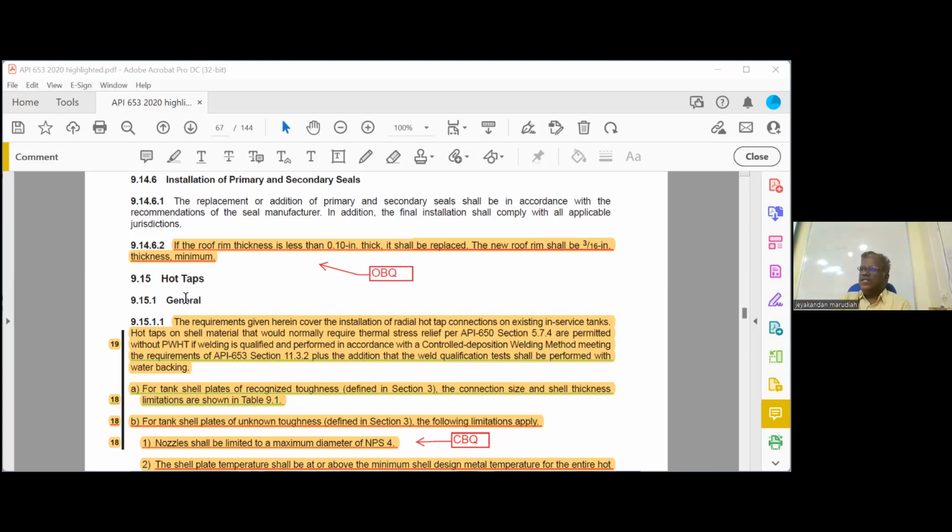That's why hot tap actual welding may take half a day, but we have to qualify the procedure first. We have to ensure how deep the welder is welding. So the procedure qualification will take more than 2 weeks. For hot tap, we have to convince that it will not cause any safety issues. Hot tap is a serious issue. The thickness and everything you have to establish first. Generally, they will use a very small diameter electrode, 2.3 mm, for hot tap welding.